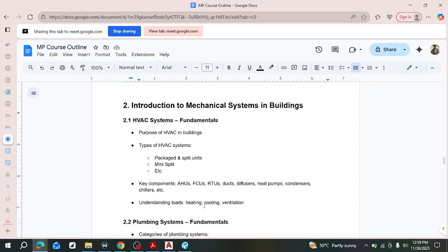When the air flows over the cooling coil, the content of that cooling coil increases in temperature. There's a cycle where it goes back to the outdoor unit to release the heat it has collected. The unit that handles just the air, with the cooling coils and heating coils in it, is called the air handler. FCU is also a type of air handler too.